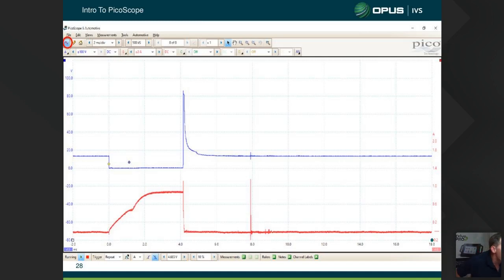All right. So this little button on the side, we can change between scopes. We might have two oscilloscopes plugged into our computer so we can achieve more channels, or we might be measuring two different things. This little button allows us to change between scopes or to change to the demo software and back to our original scope. We might have an old 2-channel scope plugged in, and we might have a new 4-channel scope, which means we've got 6 channels we can measure.